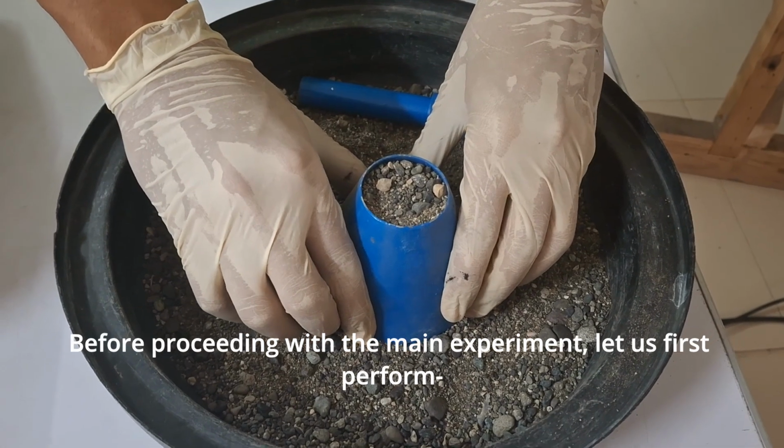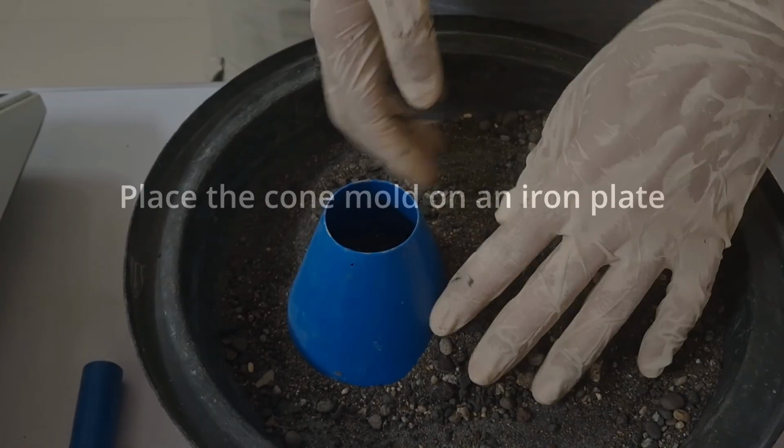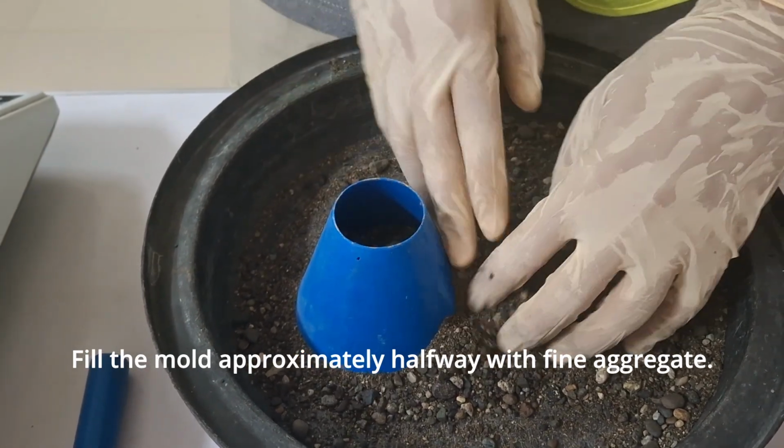Before proceeding with the main experiment, let us first perform the provisional cone test. Place the cone mold on an iron plate, and then fill the mold approximately halfway with fine aggregate. Lightly tamp the material with about 10 drops.